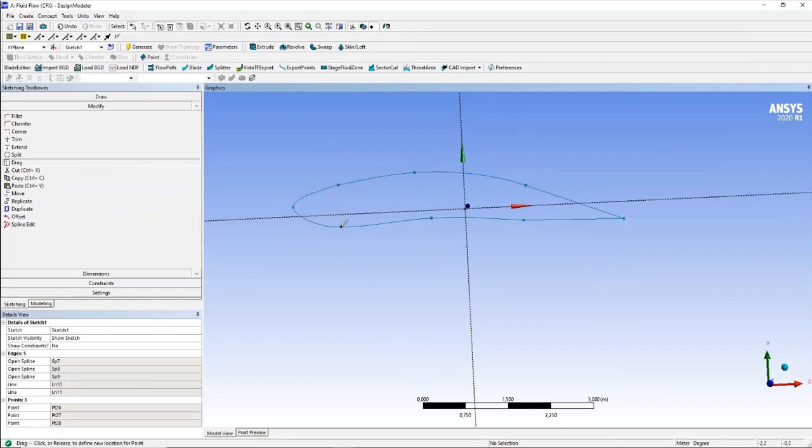Okay, now before we go on, before we do our mesh, there's one additional thing I want to teach you. I want to teach you how to use the dimensions. Now, I think our airfoil is pretty cool now, and take care that all the splines are closed. If you have any holes here in the wing surrounding, then you probably can't do the model later.